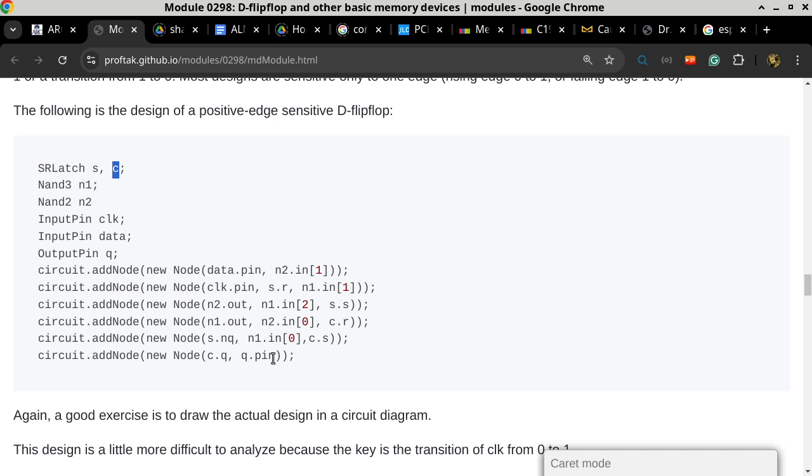You can always leave an output pin not connected to anything because it is not useful to you, but you never leave an input pin not connected. Because if you leave an input pin not connected, the input is still used by whatever device to determine the output. So having an input pin not connected to anything means it is quote unquote floating. In electrical terms, it's called floating.